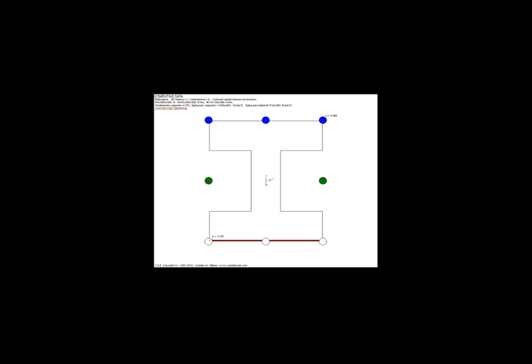In effect, this simulates the rotation about the lower side of the bearing surface. The affected part of the bearing surface is much smaller, yet the peak stress is almost 10 times greater: 4.375 times the bearing support's limit stress, compared to 0.495 times in the previous case.